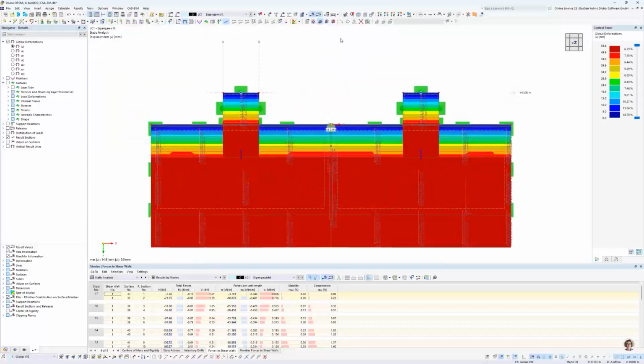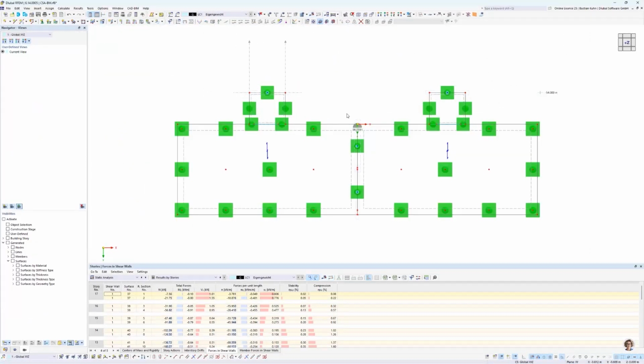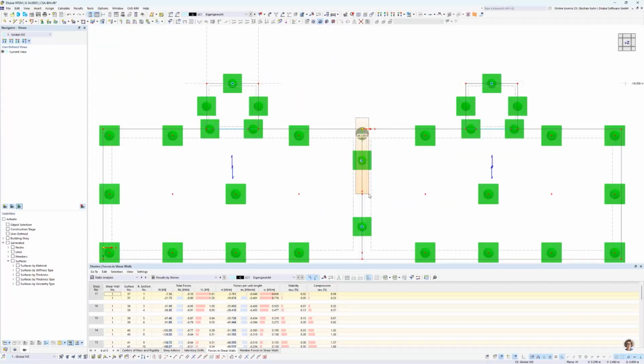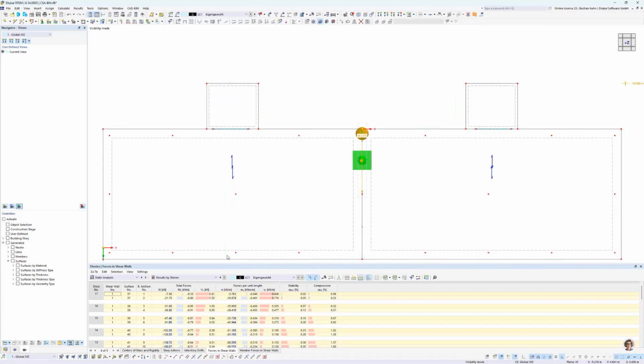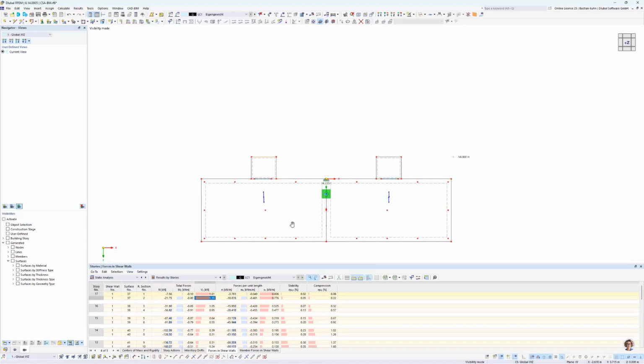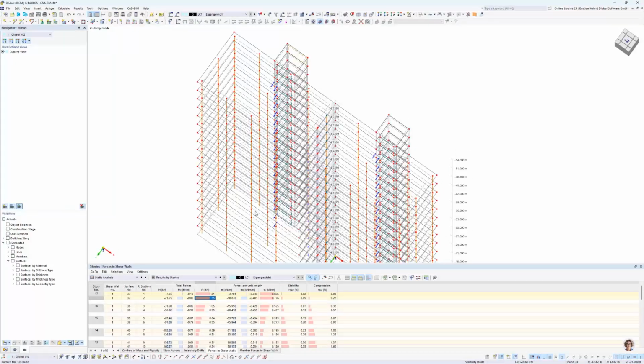When we maybe go back to fly mode and select just the timber frame walls, visibility by these ones, and when we just display them. Okay, once again, we do not have horizontal force, but you can see that you have for each one the horizontal force, and this is important information for the timber frame wall.